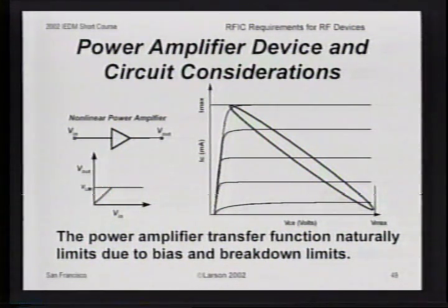In a typical CDMA power amplifier today, probably 97% of the DC power that's drawn from the battery by the power amplifier just heats up the phone. Only 3% of that power goes out of the phone into the antenna. So most of the time when we're talking on the phone, all of that power, instead of going to the base station, is just warming up your hand while you're talking. So you want to operate these devices as high in efficiency as you possibly can.